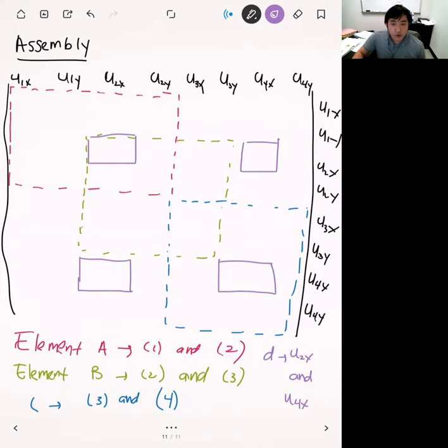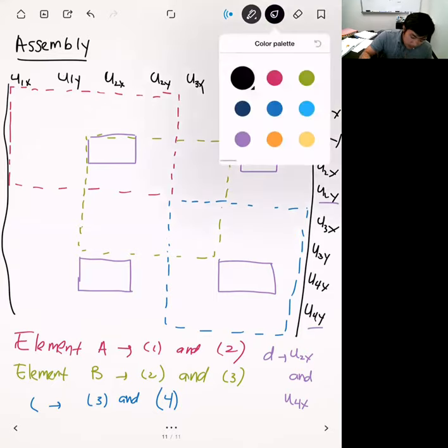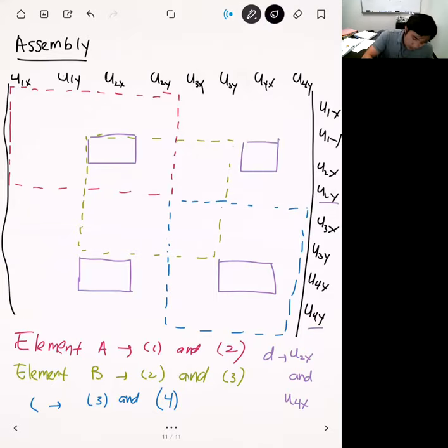All right, and so we insert only 4 entries into the stiffness matrix because our element stiffness matrix was only 2 by 2, okay? And so if you're going to use that shortcut, you have to be careful in this. And you have to be careful, because our element was horizontal, not to make any entries in the Y degrees of freedom. Okay. All right. And so let's go ahead and add all our entries in here. Okay. All right. And so I'm just going to do the result of all of these.